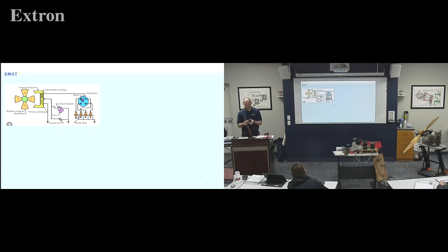What's interesting on a high tension, remember this is high tension because we got primary, secondary with a transformer in here, is there's ever so slight a gap between this distributor point and the wire for the spark plug. So guess where else you're getting a spark every time you get a spark? You're getting one in here, but the gap between this and this is tiny. The spark that jumps across here, we're not really counting as much of anything, but it's there.